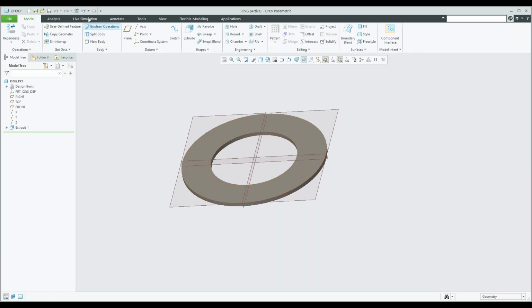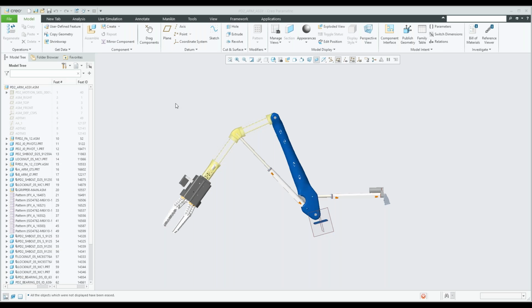One of the other nice ones in Creo 8, which I found pretty cool, is the ability to make solid bodies transparent, and quilts and tessellated bodies. With Creo 8, and I think a certain build of Creo 7, they've added this multi-body capability. So you can have two solid components within one component, if that makes sense to all the users. I think the newer guys will grab that a lot quicker.